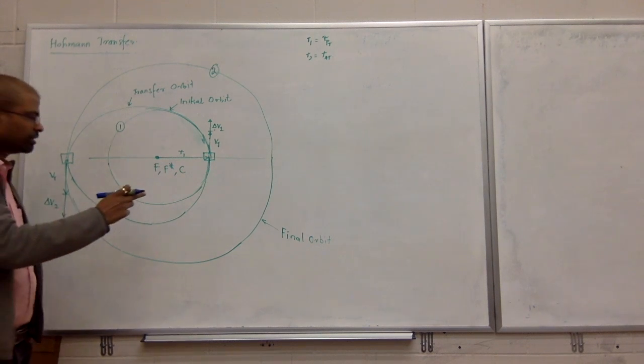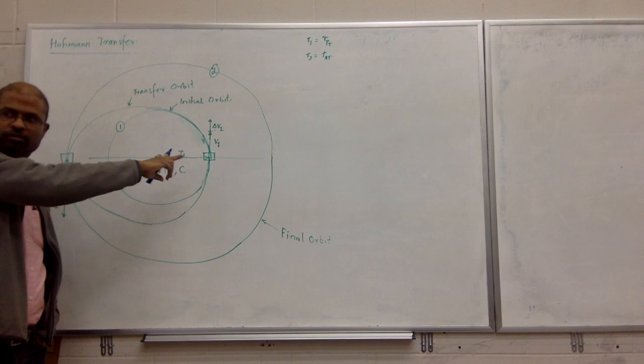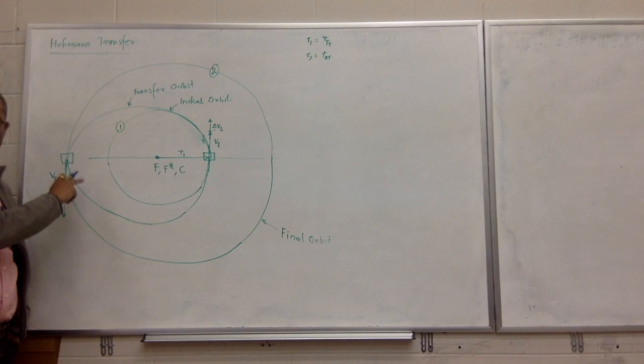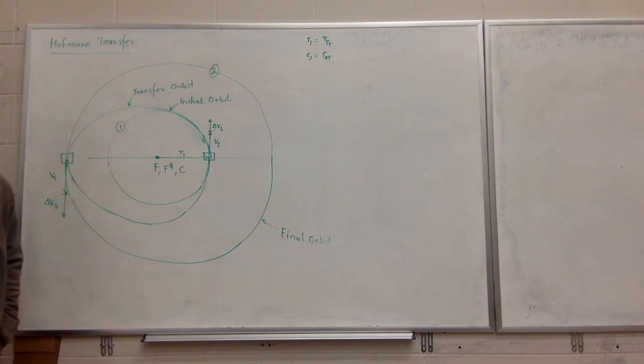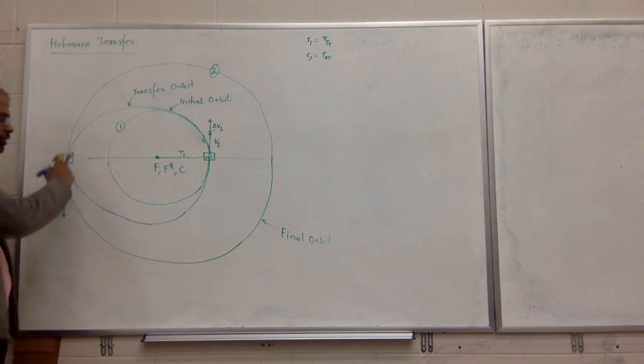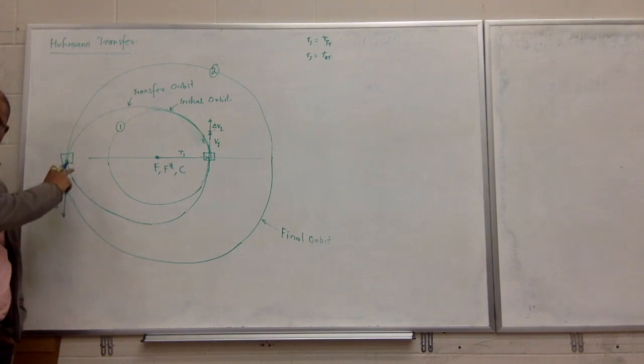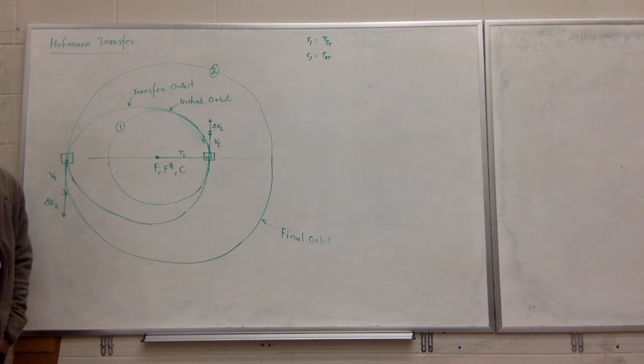So what can happen is, you may fire your thrusters here, right? It gets into this elliptical orbit. But as soon as you come here, you can fire your thrusters again. But if you want, you can take a couple of laps, a couple of orbits. Just make sure you're okay, and then fire the thrusters when you have to, when you come here. You got it? It's very critical that you fire the thrusters at perigee and apogee, or periapsis and apoapsis.